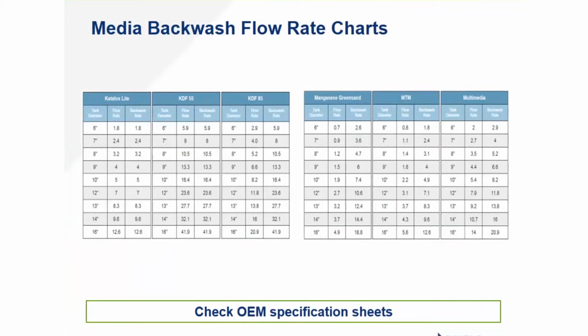either increase the backwash time or lower the capacity. Question: You're finding it frequently on 13-inch tanks and above. Yeah, that's one of the hard things about balancing, in a practical sense, in residential applications for iron removal: how much capacity can I get out of that tank?